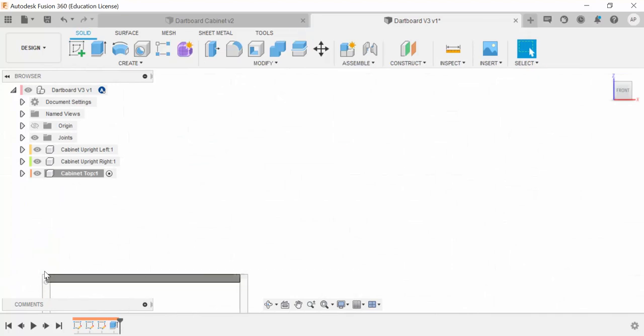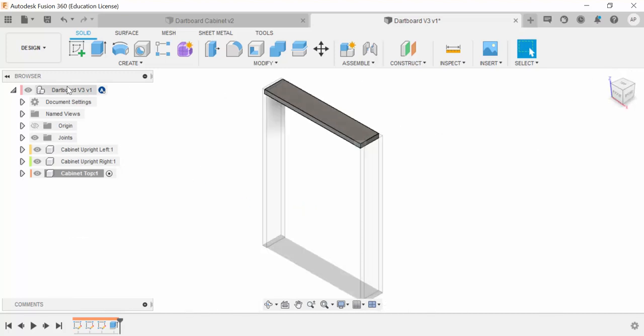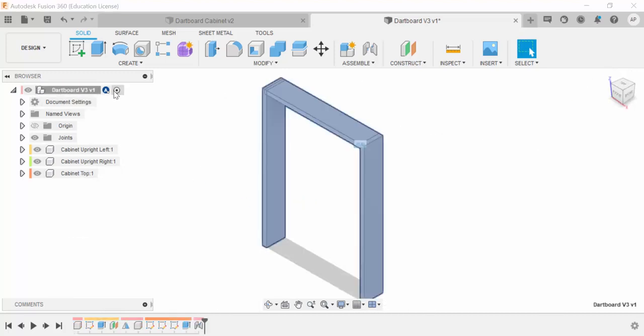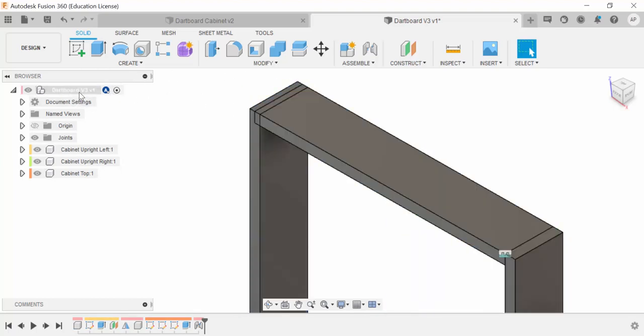Finish sketch, and you'll see that over here it's gone 10 millimeters into my job. If I click at the top, click on all sections of the job, I can see the two pieces of timber that are kind of crossing each other there.